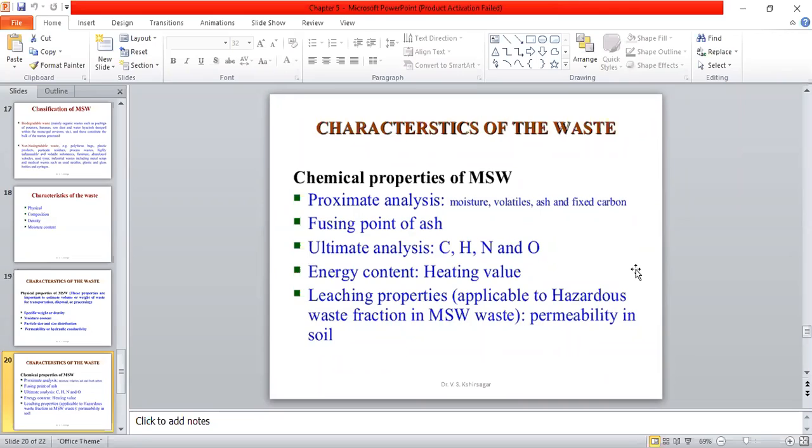And the amount of CH4, or the methane, present in the biogas is in the range of 60 to 65%. Means around 30 to 35% are the impurities present in the biogas, and hence its burning capacity is less. Whereas we will compare that gas with the LPG gas, which we are using for preparation of food on a regular basis. In the LPG, whatever burning gases are available, these are 100% available, because whatever impurities were present in that have been removed by filtering media or by performing some processes on the same. And that's why its burning capacity is more, and its heating value is great.